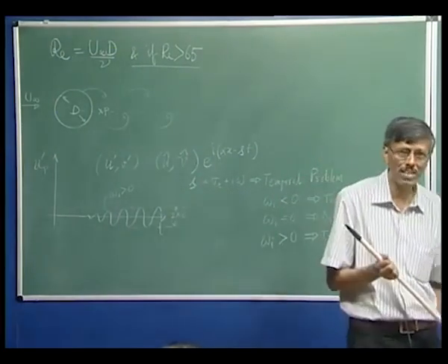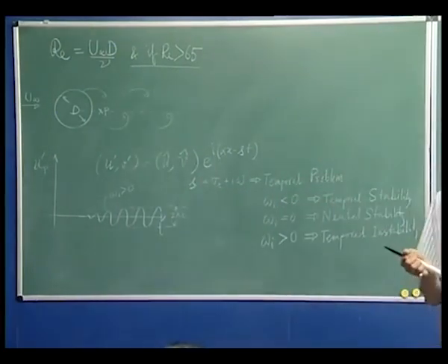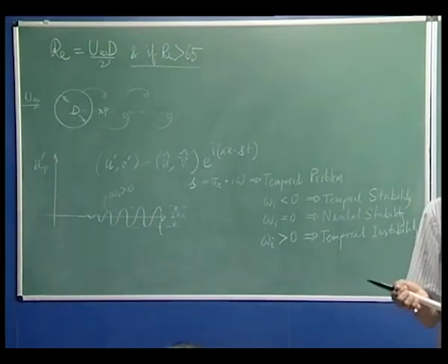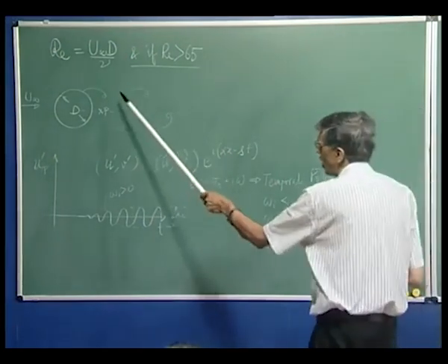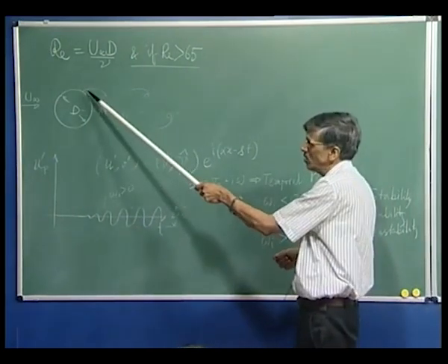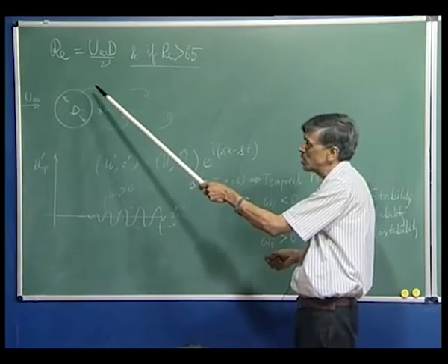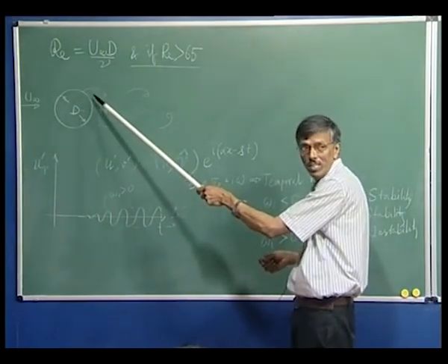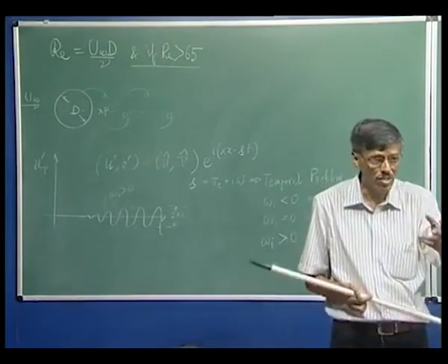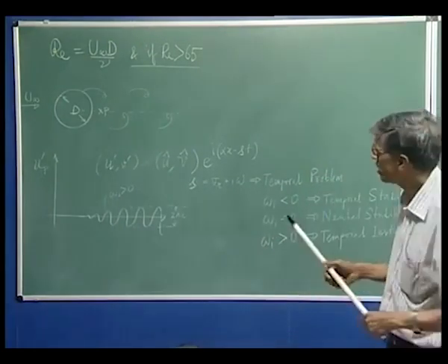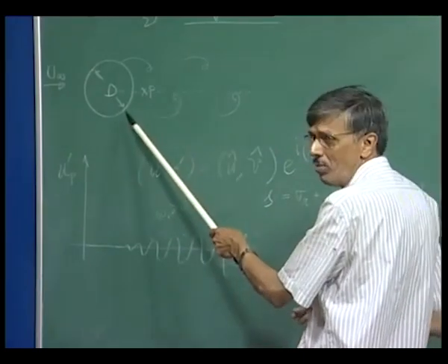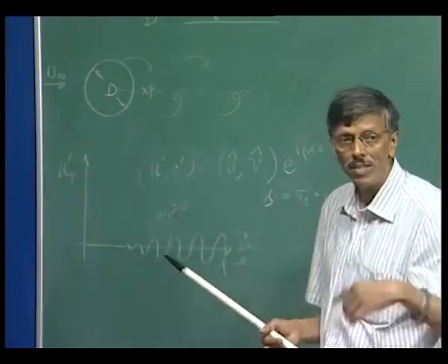So what you are seeing is vortex shedding, and as I told you yesterday, it's like your fluid dynamical pendulum, right? What you see is alternate shedding of vortices. That means you have some separation bubble forming here, a recirculating region, which grows differentially on either side, and once it reaches a certain amplitude, that is detached, while the other one, which was small so far, takes up the throne.